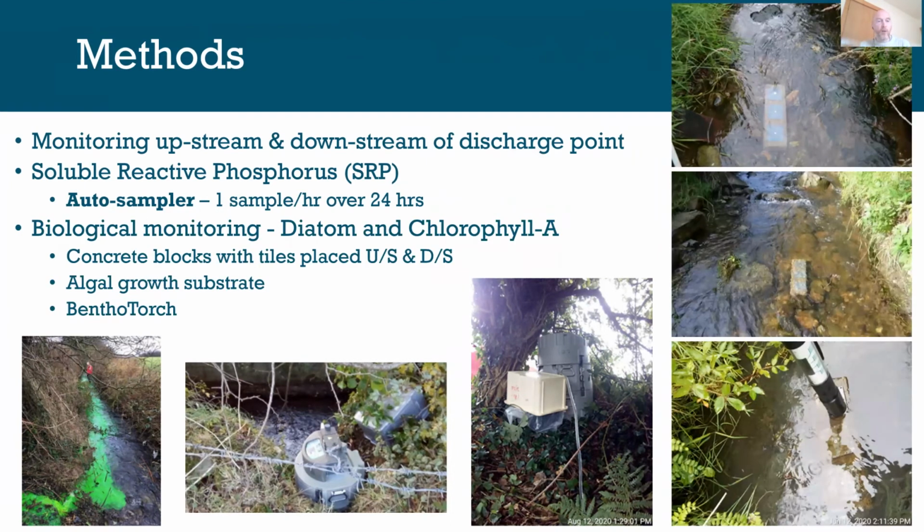We're also conducting biological monitoring at the Liscooley site, looking at the diatoms that are occurring. We've got concrete blocks placed upstream and downstream of the discharge location, and these serve as an algal growth substrate. The algae grow on the tiles, on the concrete blocks, and then we come along with the BenthoTorch, which you see there in the bottom picture. That gives an in situ reading of the concentrations of diatoms growing on the tiles positioned at the site at Liscooley.